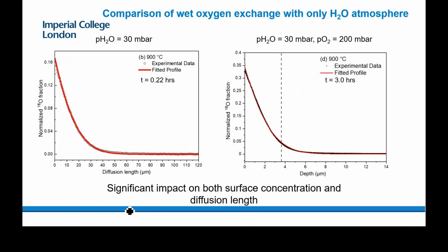Deposit a couple of electrodes. Now that can either be the electrodes that you're measuring in your fuel cell, or it can just be platinum or silver or gold or whatever you want. So deposit a couple of electrodes on your electrolyte, a couple of mesh current collectors in your impedance analyzer, 2 electrode measurement, and just get on with it.